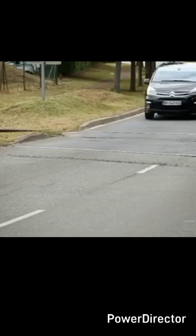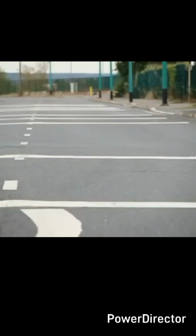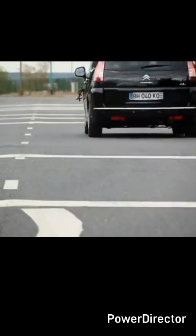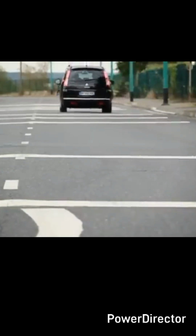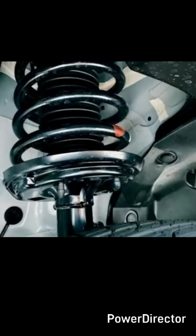Springs act as reservoirs of energy. When the vehicle passes over irregularities of the road, it compresses the spring. This energy is released when the spring subsequently expands, and with the help of dampers, the energy is converted into heat, and the spring absorbs the shock and avoids transfer to the vehicle frame. There are three types of springs used: leaf springs or laminated springs, coil springs, and torsion bars.